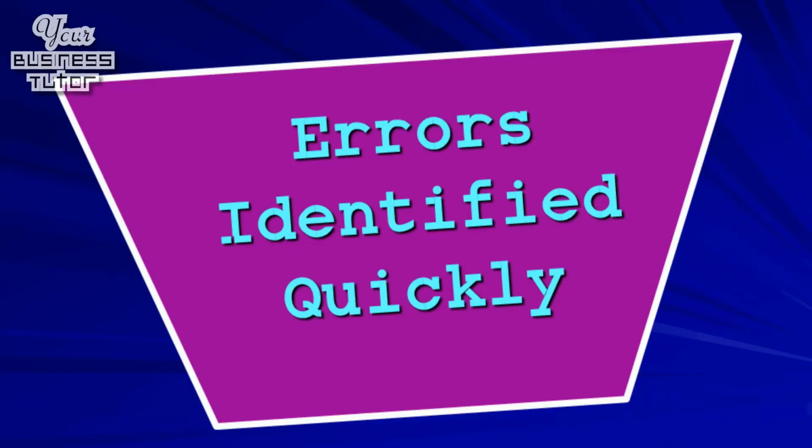Given this, and as you have probably already realised, a big advantage of a quality assurance system is that it attempts to reduce the high levels of waste that can result with a quality control system. In that, by checking quality throughout the productive process, errors will be identified quickly, meaning fewer items will have to be reworked or scrapped. Further still, because regular checking will make it easier to pinpoint errors to particular points on the production line, less time will be needed to solve any problems, meaning if manufacturing needs to be shut down, it will only be for a short period of time compared to quality control.